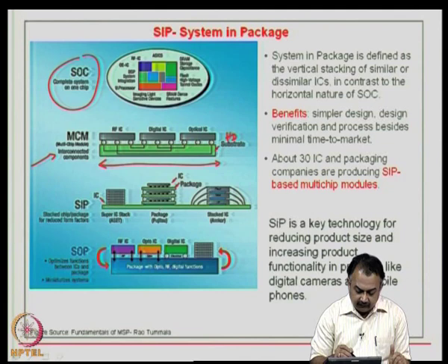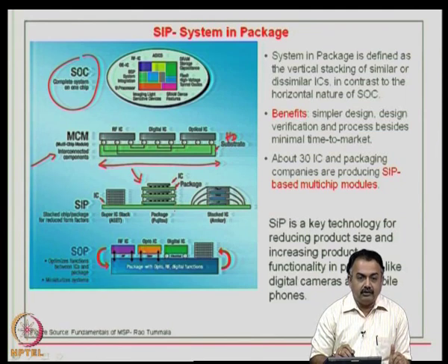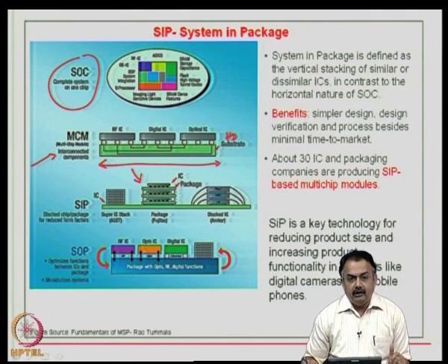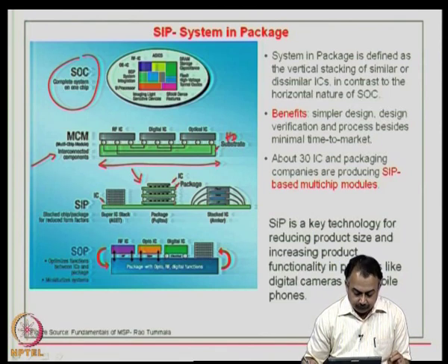If you look at this package, for example, companies like Fujitsu, Amkor and many others bring out these custom built system in packages. So, here you can see in this particular block that the ICs are vertically stacked, and then interconnected again to a common substrate. They can also be interconnected to the adjacent dies. So, the design would involve establishing interconnects either by using wire bond or flip chip interconnects.